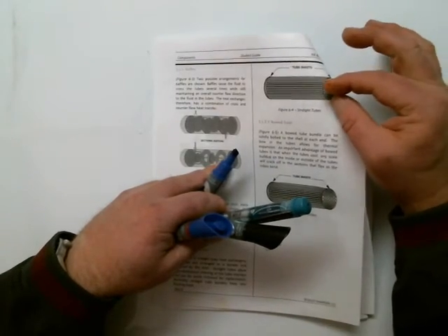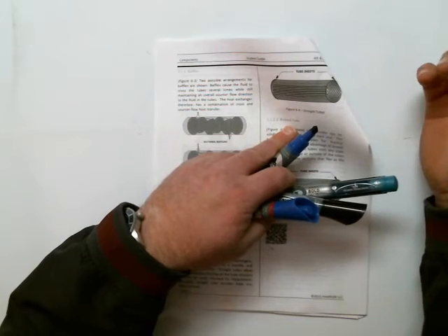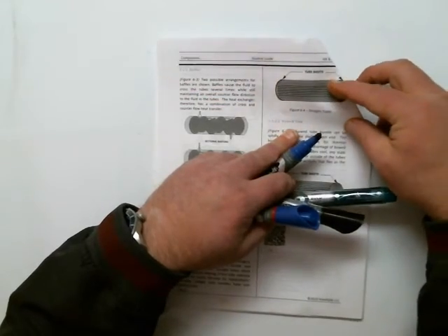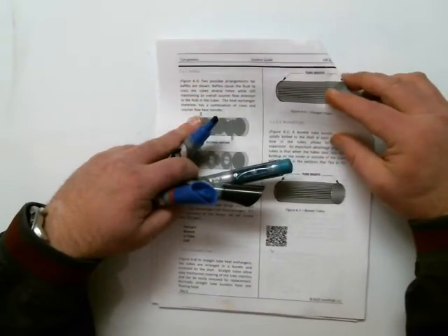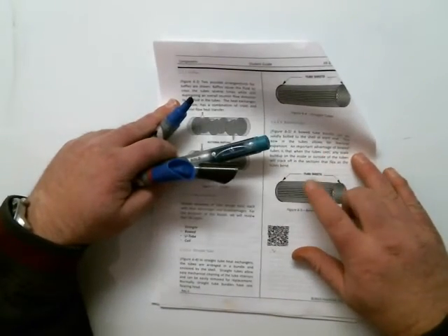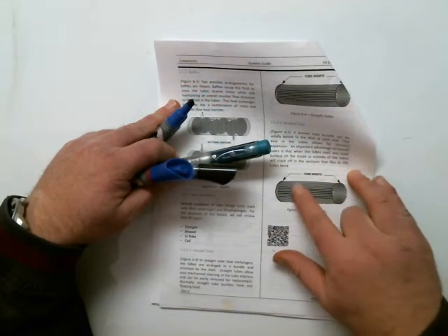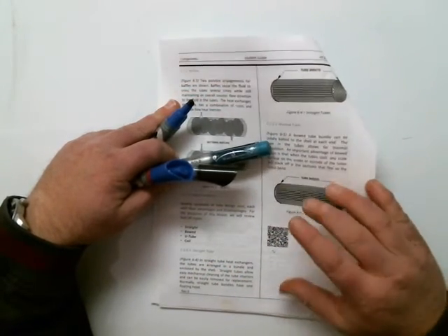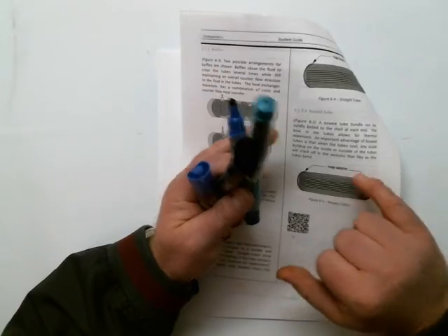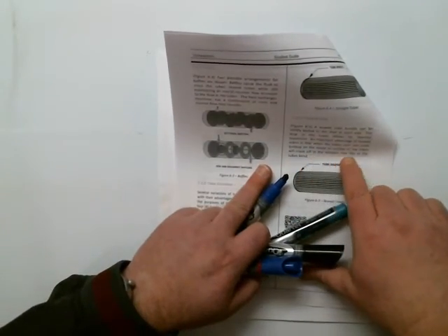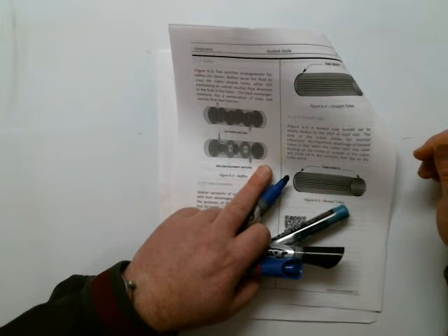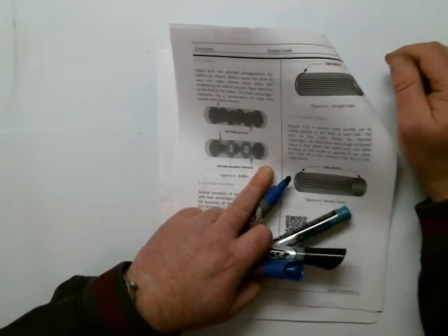We could put little balls in there, like a lot of plants have what's known as an Amertap system. I could put little balls in there and they would go straight on through, and they could mechanically clean the inside of the tubes and remove any debris or buildup that's occurring. Another one is straight in nature, but it's bowed. This is pretty cool. Bowed tubes tend to expand when they get hot and then contract and bow. That has the advantage of cracking off any hard scale buildup that tends to build up on the outside of the tubes. So you'll see a lot of these in the plant.